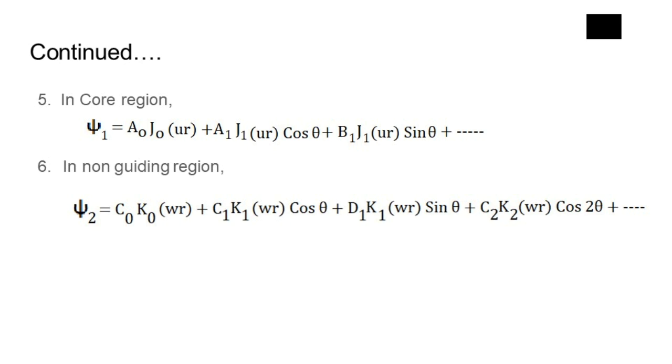So we can say A and B may be joined by a straight line to make the guiding region distinct from the cladding. We may also decide not to join A and B, but in this case the core-cladding boundary in this region will not be well defined. The coordinates rho, phi on AB can be easily determined by numerical techniques. So in this way we shift the origin to the new origin.